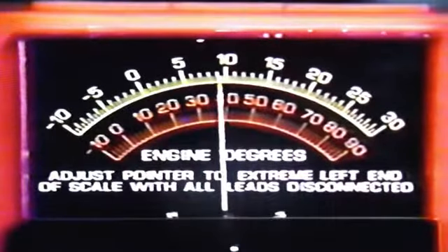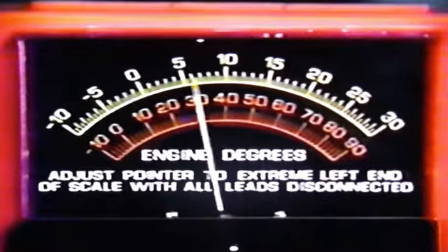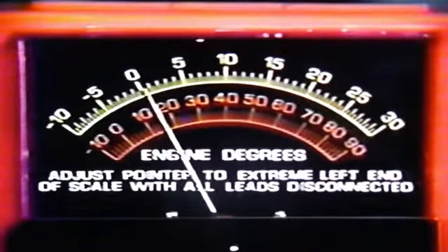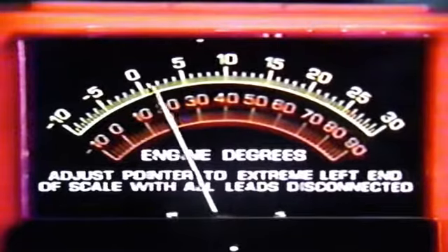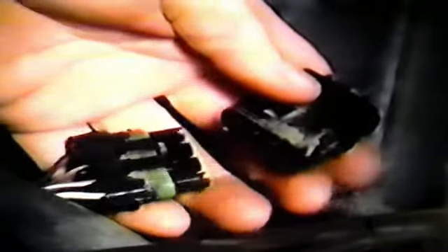Timing is critical to a 3C engine. Experience has taught us that the best way to check timing is with a magnetic timing device. Lights are just not accurate enough for the critical adjustments we may want to make. Ideally, we'd like to be within just 1 degree either way if possible. The first thing we need to do is unplug the 4-way connector at the distributor. We have to get the computer out of the picture so that we can turn the distributor to set our timing.